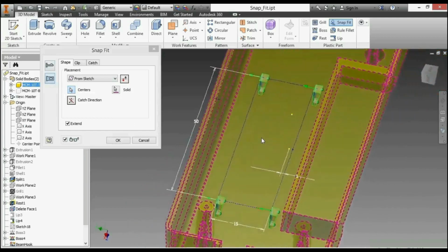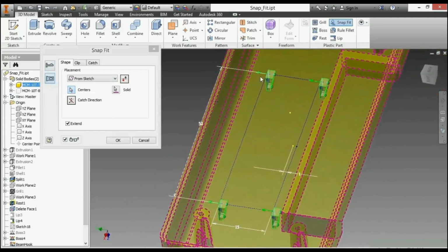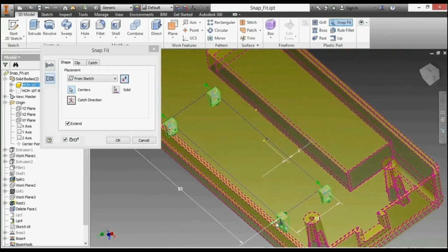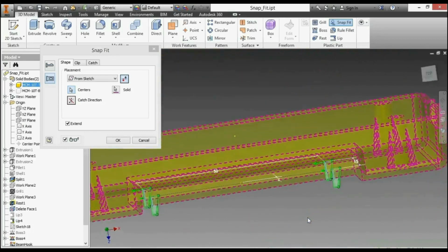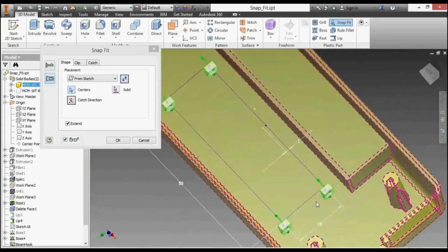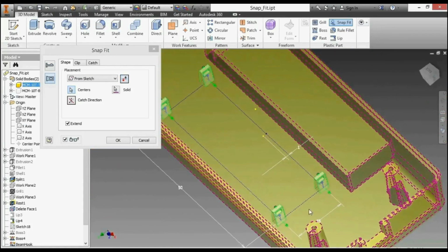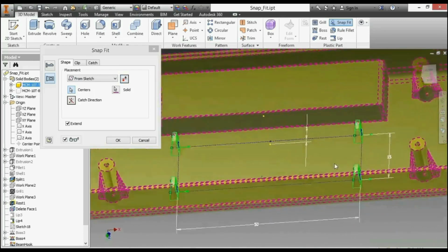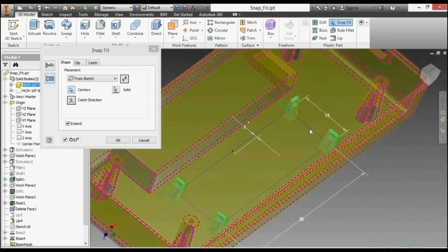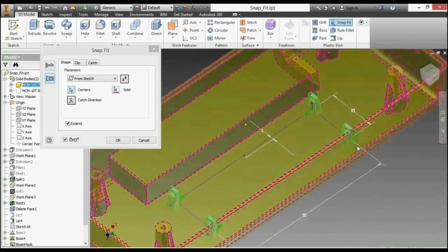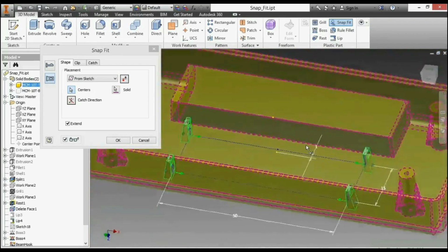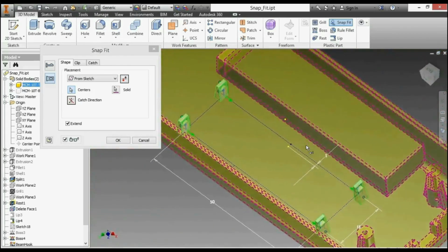And what you're noticing on these is a bunch of additional arrows. We can click on these arrows to adjust the geometry of each independently. Now currently these are going to the outside of the geometry. I want them coming to the inside. So again, there's another arrow on the inside there. And if you need to keep flipping them, just keep clicking your green arrows. I want these all facing to the inside. So now I'll start adjusting our geometry.